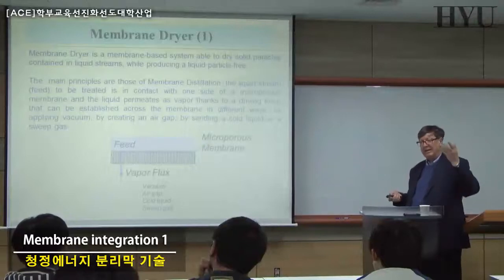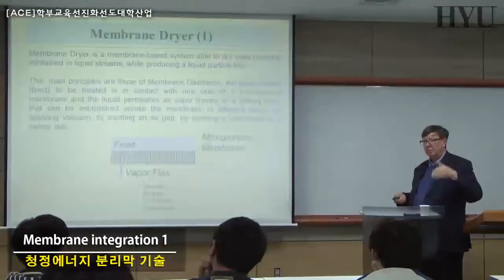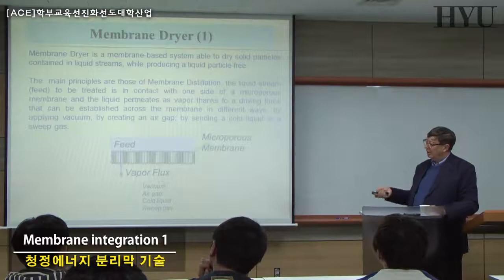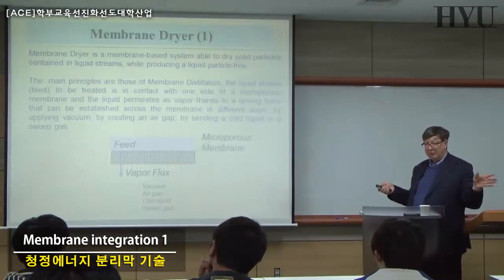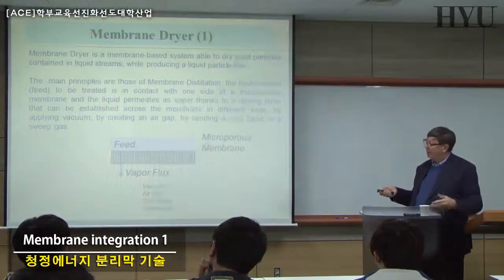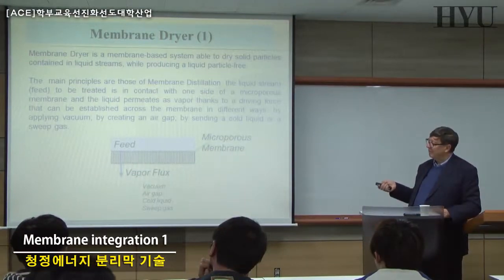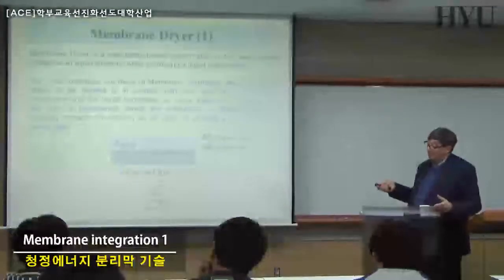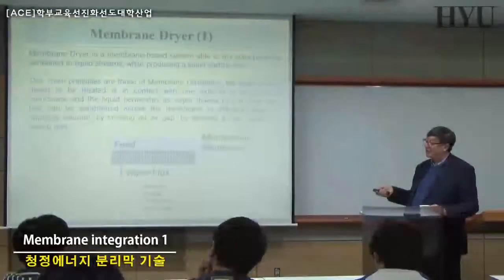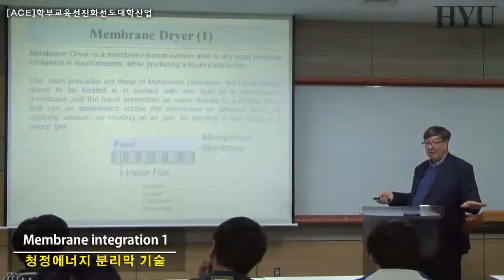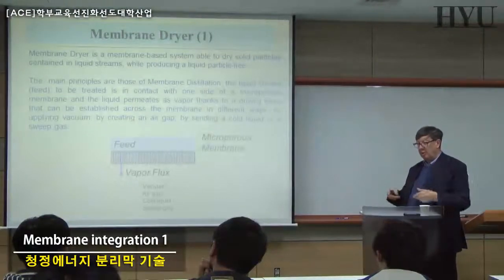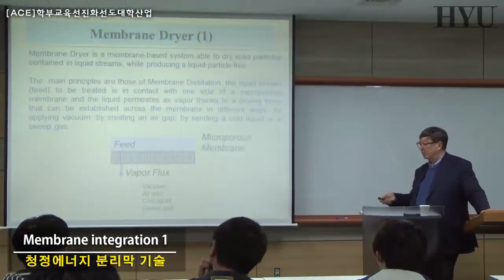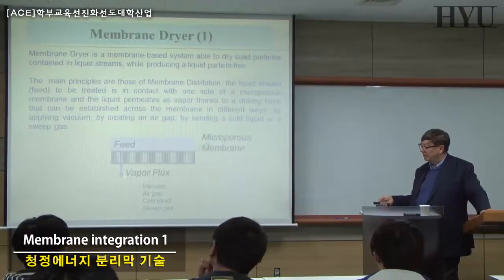Lyophilizers normally work at 80, 90 degrees centigrade to remove all the water to have powder. You can make the same operation with the same membranes, having a powder as a fluidized bed, etc., using your membrane distillation microporous hydrophobic or also hydrophilic. And you can just extract the water as vapor at 20, 25 degrees, so minimizing all the trouble related to the crust, to this cluster formation, etc., etc. And quite interesting also this one.